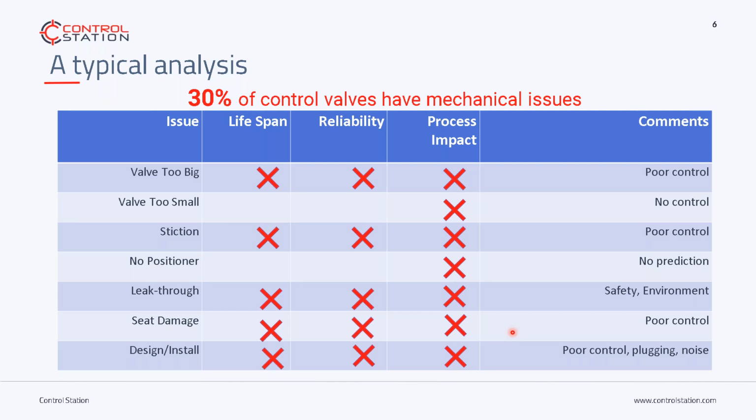Seat damage can radically affect your process. I spent some time in the offshore oil industry, and wellheads can be screaming at you, but they are designed to take those velocities and that erosive material. In normal process production, noise is not good on a valve. If you hear valves whistling or whining or any kind of noise, it should be investigated. It's not going to cause short-term problems, but it will certainly add to long-term reliability and maintainability issues.